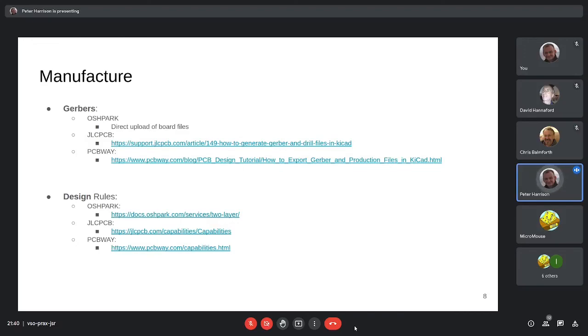If you order them from JLC PCB or PCBWay, they have instructions on how to generate the Gerbers to their specification, and they have specific design rules pages for your reference. Either of those will deliver. You can have 4 of these per panel, 5 panels delivered to you for about $25. So you could get 20 of these for about $1 each or £1 each or something. If this one works, we might send them out. But Ian's done a 4-sensor board as well, haven't you?